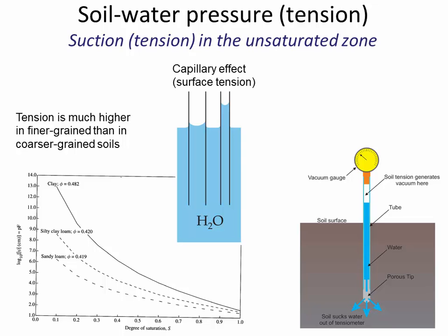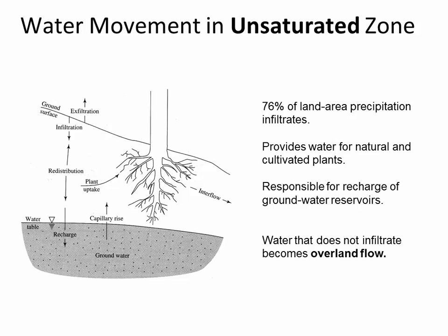So sometimes we think that what's getting the water into the ground is there's a pool of water, you know, sort of like a pond, and that's what forces the water down. That can, but that's not all of it. The water is actually getting sucked into the soil by the soil. But during the rainstorm, as those soil voids fill, as the saturation goes up over time, then the suction decreases. And we'll see that when we look at some diagrams of infiltration over time.